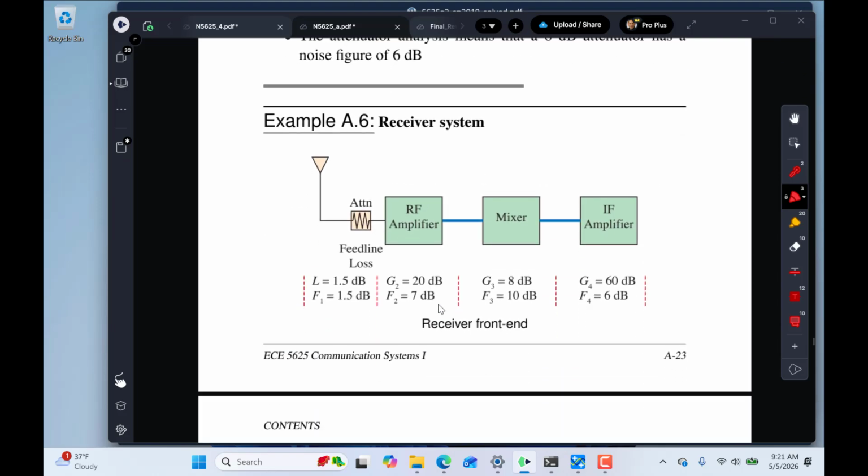And this is a little example that's in the book, and I put in the notes. It just says, suppose you have an attenuator right up front. Did you put that there? No. Did the feed line do it? No, so you have loss in your cable. That's what we're talking about here, feed line loss. You didn't want to put it there, but it ended up being there because there is some loss. So even 1 dB of attenuation in a feed line is a 1 dB noise figure hit right at the start of your receiver. So it does matter.